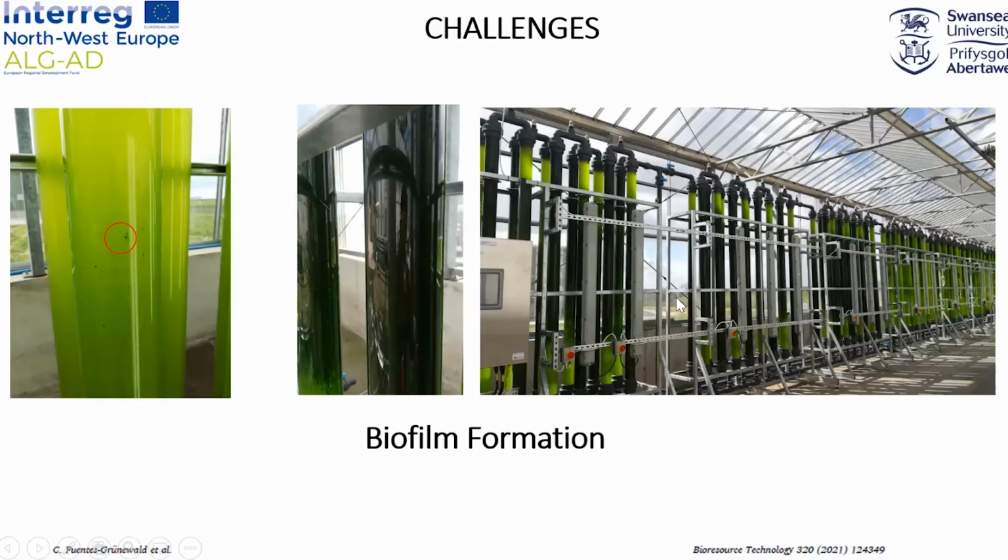The good thing, as Darren mentioned, is that this is a sectionable reactor. So basically, we can sectionize this reactor and clean each of the modules without stopping the reactor itself. So in this case, we stop these 3 modules, we keep these 4 running, and we clean this one, and then we clean the rest. So that is a really good way to tackle this biofilm formation.